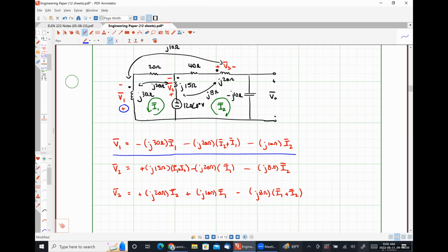For the second term, because the positive polarity terminal of V1 is at the undotted terminal of coil 1, what we're trying to find is the current flowing into the undotted terminal to give us a plus sign out here. Well, the current flowing into the undotted terminal is I1 plus I2. So actually, this one should be a plus sign because the current flowing into the undotted terminal is I1 plus I2. So that was me messing that up a moment ago by not recognizing that the currents were flowing in the same direction through that. So it's a good thing we went to look at this.